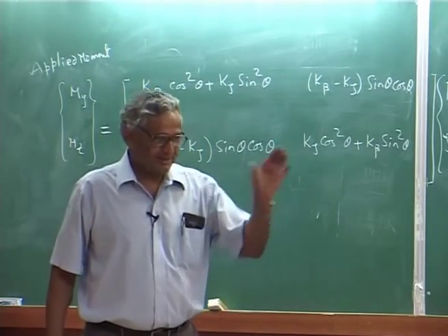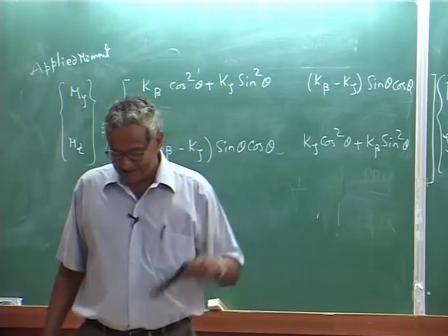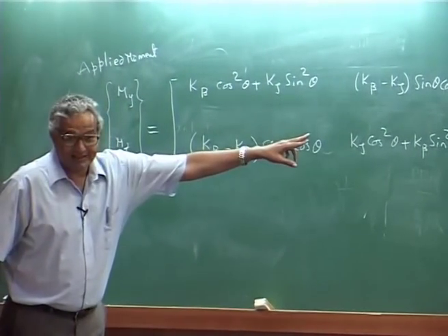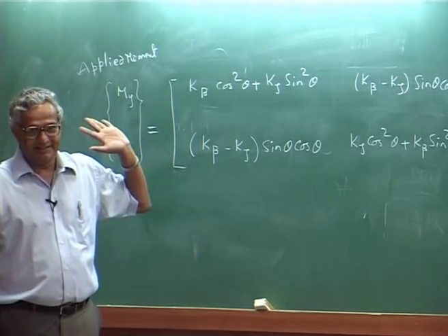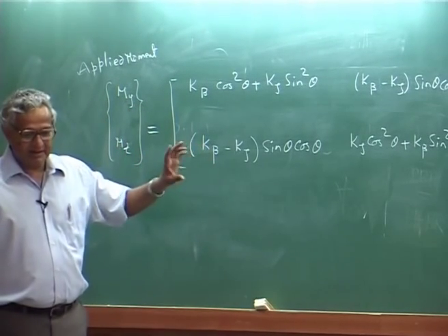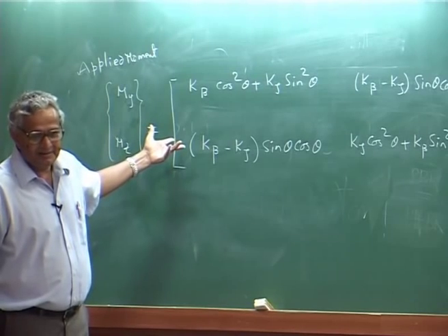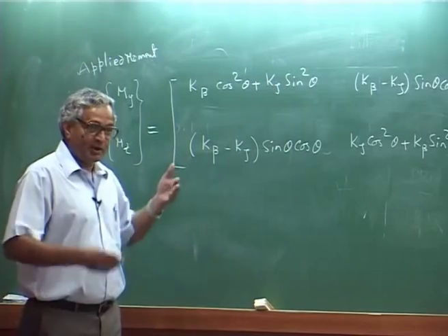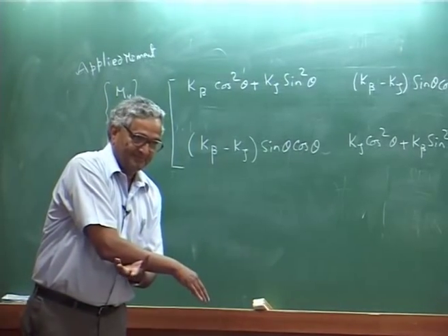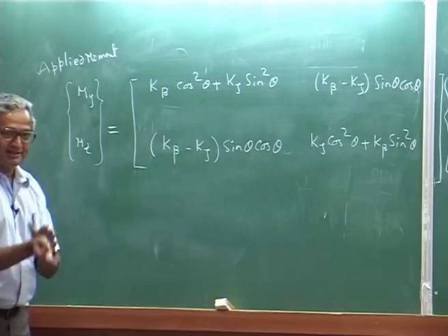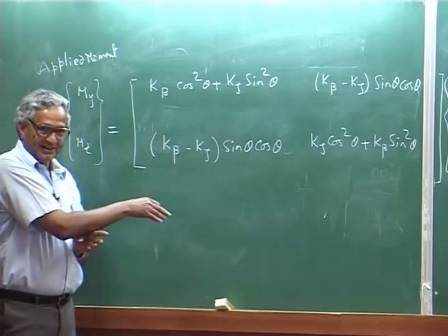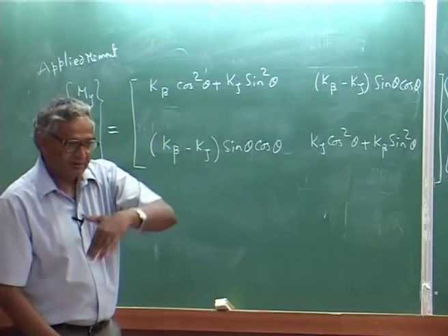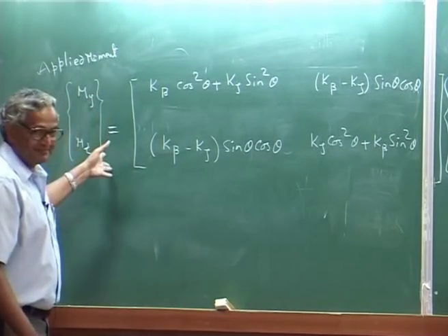Finally, all will come out to be the correct equation. Only thing is, do not take it as though this is following that convention. If you modify the convention and apply restoring moment, this is the applied moment. Restoring moment means what the spring gives on the blade. This is what externally you apply on the spring. You can take what is the spring load that comes onto the blade, then you will put a minus sign,